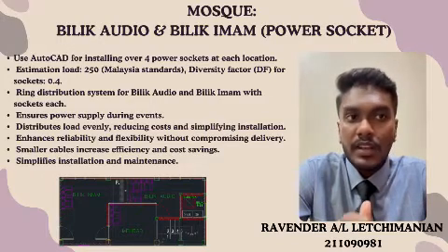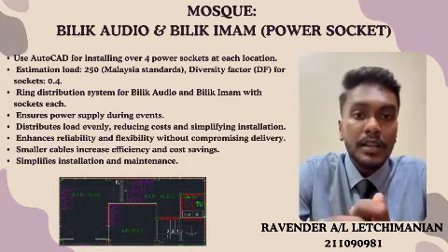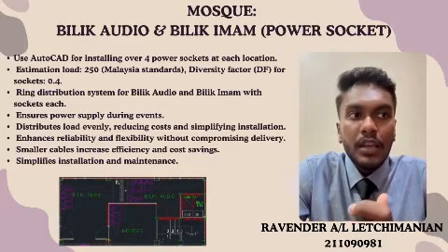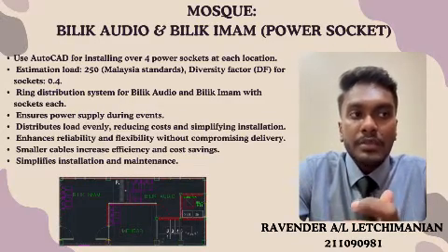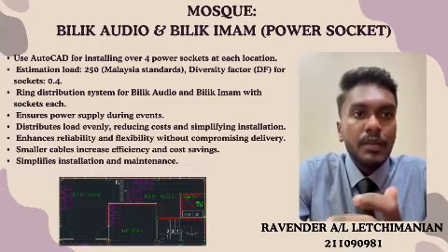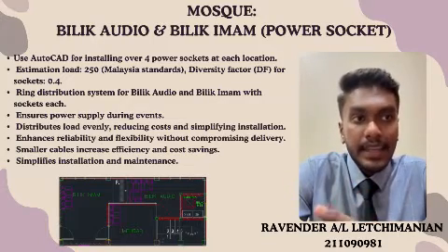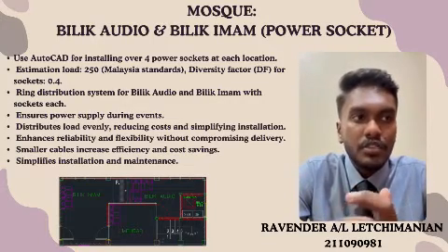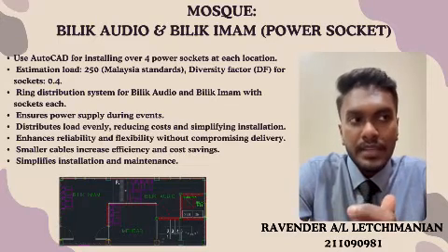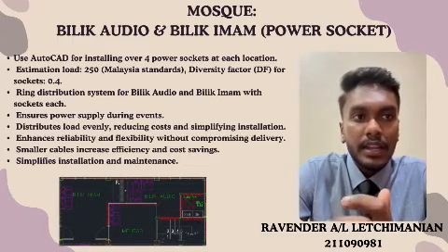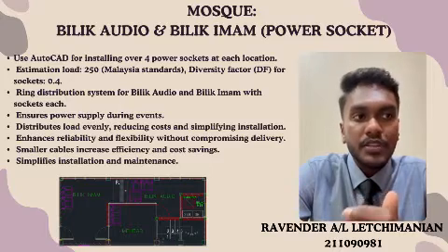We have installed 3 sockets of 2 times 13 ampere switch socket outlet for the Bilik Audio and 2 sockets of 2 times 13 ampere switch socket outlet for the Bilik Imam into one circuit. In this case, we use the ring distribution system for these 2 rooms. The ring distribution is the best option for the mosque.